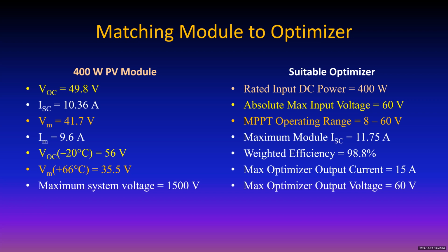So that tells you if you want to run at 400 volts, you can't get more than 60 from each optimizer. 400 divided by 60 is 6.666. So therefore, you have to have at least 7 modules in your string. Otherwise, you can't get up to 400 volts with these particular optimizers. Okay, so a reasonable match. This is where the design comes in, matching the optimizer.